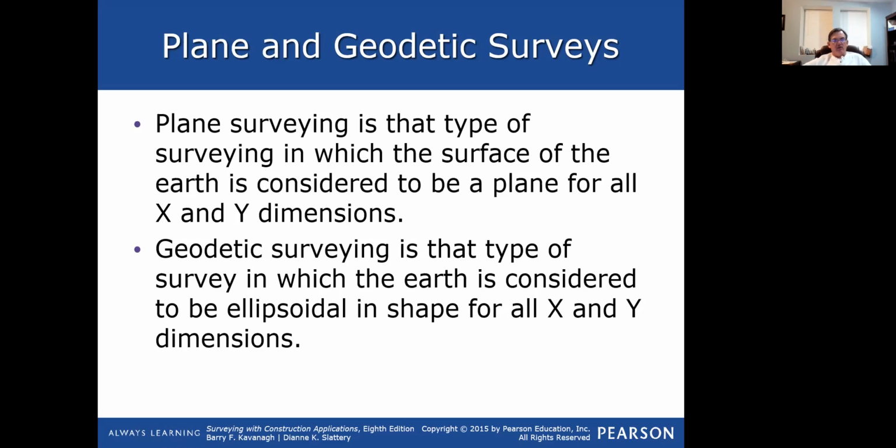And so what surveyors, engineers, and architects use for design is this: we take the Earth's surface and flatten it out into an X and Y coordinate value that can be designed from. That flattening out is called a state plane coordinate system, and it's in every one of the 50 states and in territories of the United States. It is utilized to help everybody relate to not only latitude and longitude, but anywhere else in the state. And it helps to design when you're working on a flat plane.